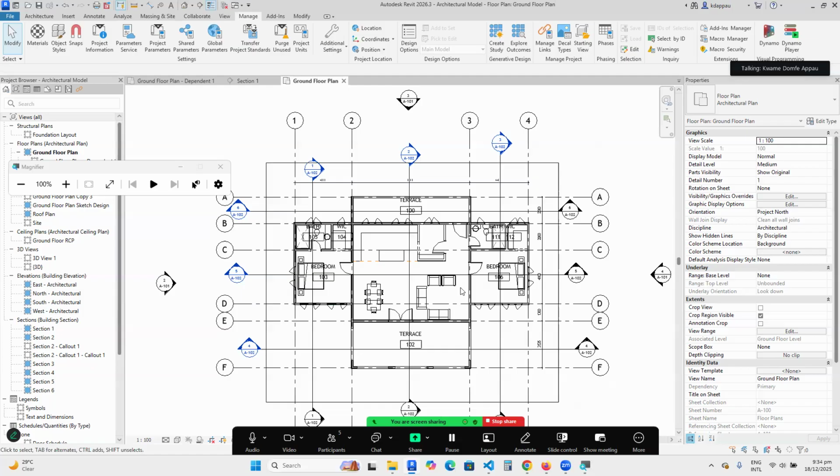Just one project. You've done all the language settings, all the font settings, all the dimension settings. Everything is complete. You have your view templates, you have your scope boxes, you have everything in them. Then that project, you can save it as a template and call it Needs template. When you save it as Needs template, you delete all the things you don't need from it.